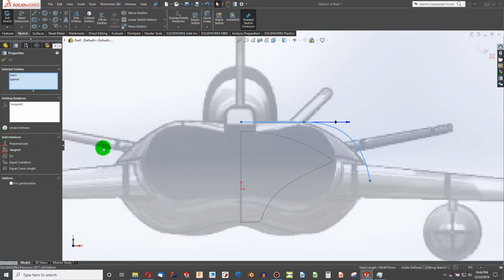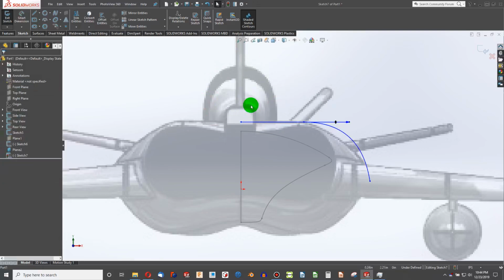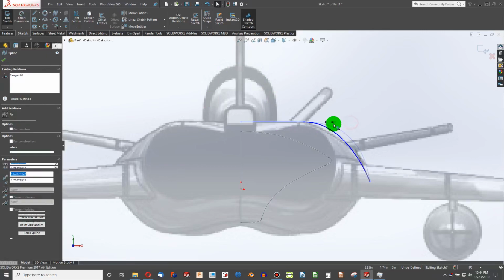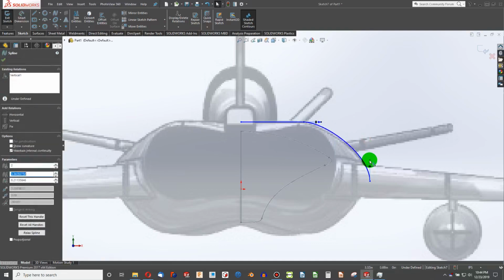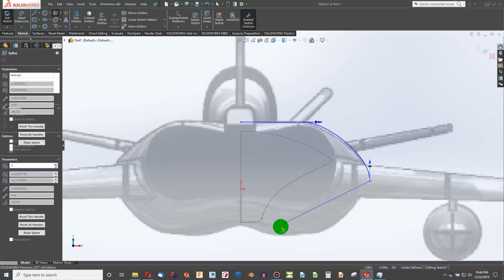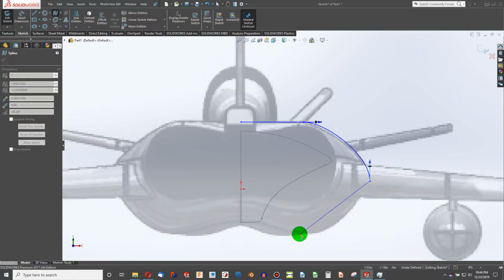So we're going to go tangent. For instance, my first time making this, I tried to include the canopy in my initial loft, and I had all sorts of things going wrong. And so I tried a second attempt. We're going to make that vertical. And my second time around, I said I'm going to do only the body, and then I'll do the canopy. And by separating them out, it was way easier. So don't be afraid to be simple. You know, keep it simple, stupid. Great advice hurts my feelings every time, as Dwight says.